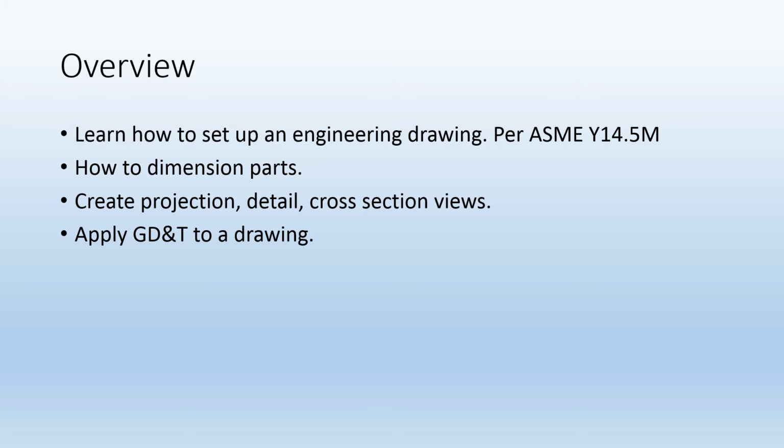They have something called perpendicularity. With this, you can, let's say, have a flat surface, and maybe you drill a hole through the top of it. So the hole would be normal to the surface. I could define the surface as something called a datum. I can tell you about that later. It's basically a reference. And I can say that the hole through that surface has to be within a certain angle. So if I give it 5 thousandths, that means there's a 5 thousandth zone which the center line of that hole needs to be in.